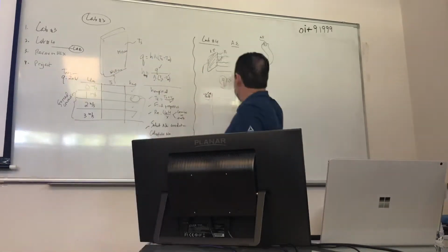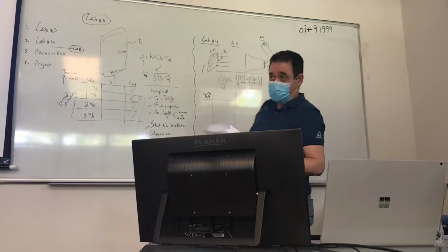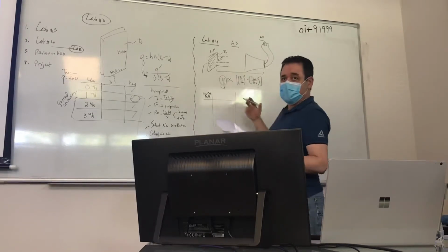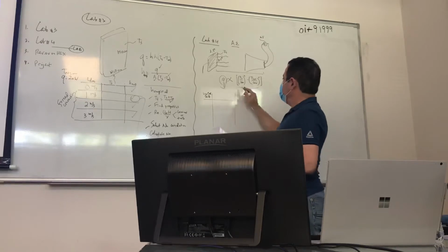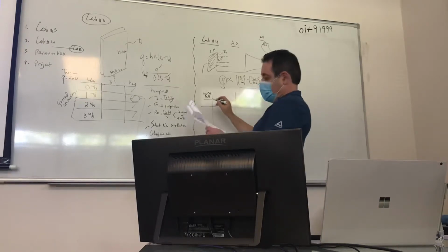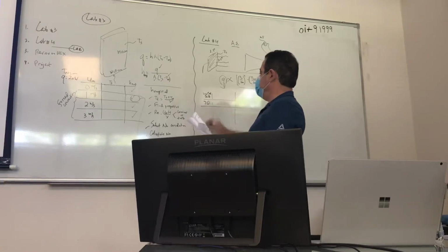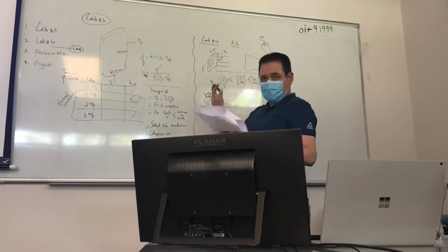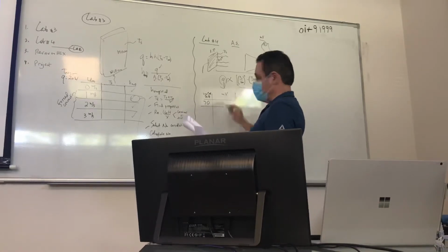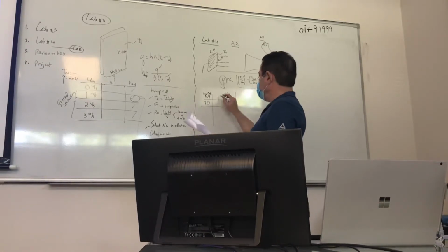So the reading out of that multimeter that we have there is essentially going to be the Q. Now, as we set the variac, I think the initial one was at 70, right? That's the highest one. And then we're gonna be reading the millivolts of the thermopile.